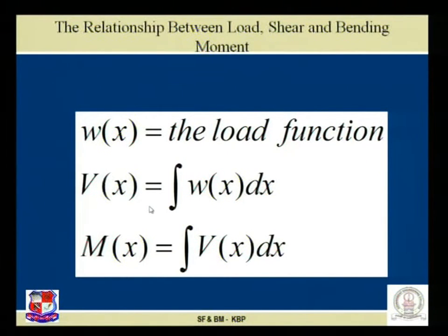So the relationship, if we summarize it in short: W, the force variable in terms of x, is the load function, then Vx is equal to the integration of Wx dx, while the bending moment Mx is equal to the integration of Vx dx.